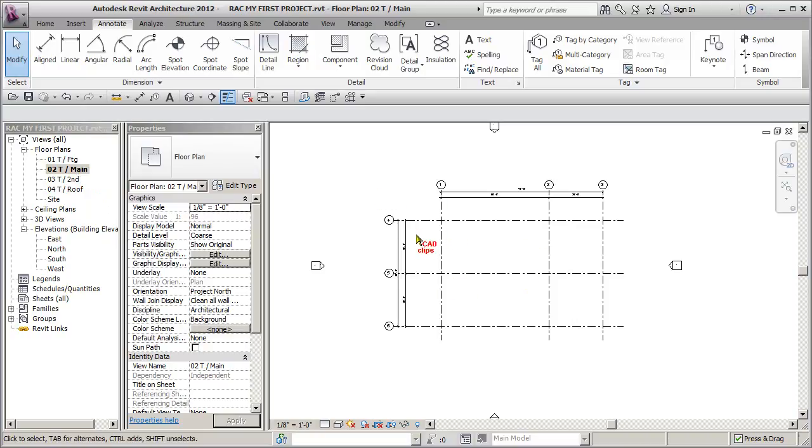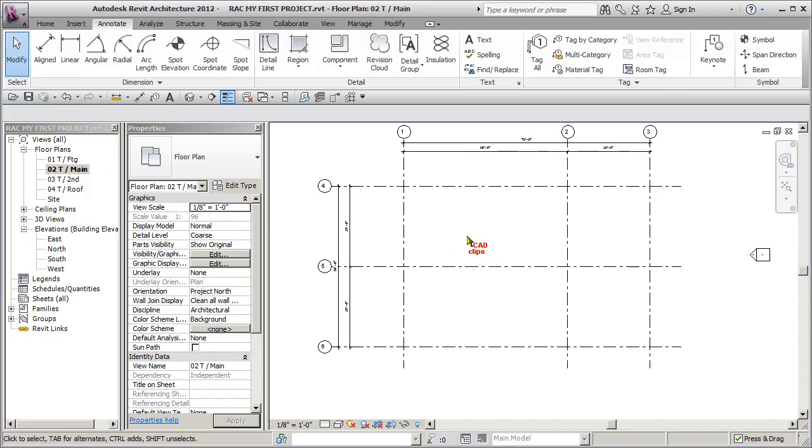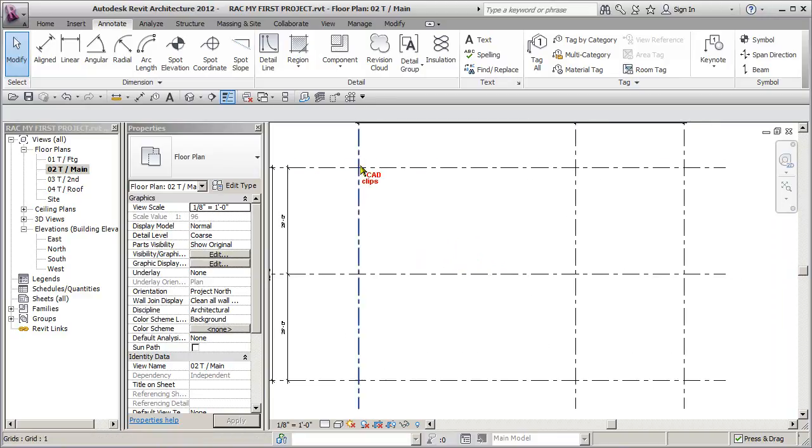By default, the floor is justified by the top. So the top of the floor will be at the main floor level, and you can vertically offset it above or below that. Our floor system is going to be 14 inches thick. It's going to be 13 1/4 inch of a wood I-joist and then 3/4 inch subfloor on top of that. And it's going to go basically to the edges of these grid lines.